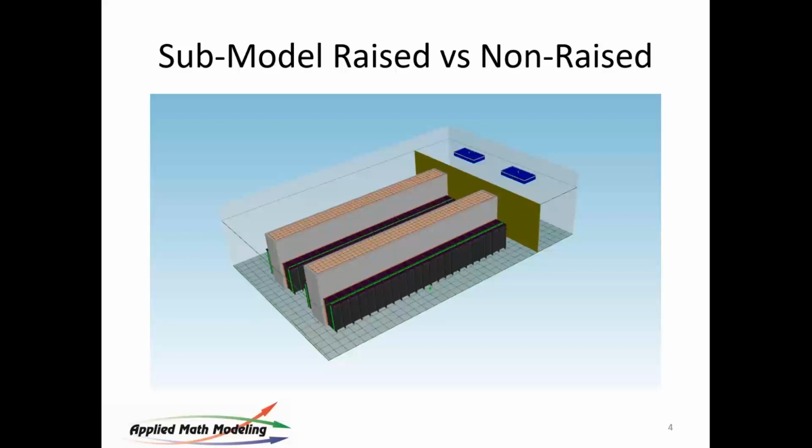Generally speaking, if you're trying to absorb outside air, the devices tend to be big because you need a lot of surface area, so these units tend to be big. And so they sit outside the data center, usually on top of the roof or some other place. They dump air into the room via some ducts, and there's usually a supply plenum along this line here that comes in. This device along the wall is generally a screen of some kind with a percent area open on it.